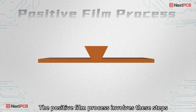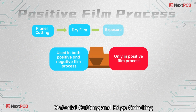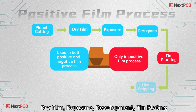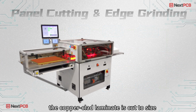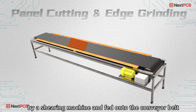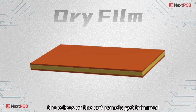The positive film process involves these steps: material cutting and edge grinding, dry film, exposure, development, tin plating, film stripping, etching, tin stripping, AOI, and impedance testing. First, the copper-clad laminate is cut to size by a shearing machine and fed onto the conveyor belt. As it moves along, the edges of the cut panels get trimmed.